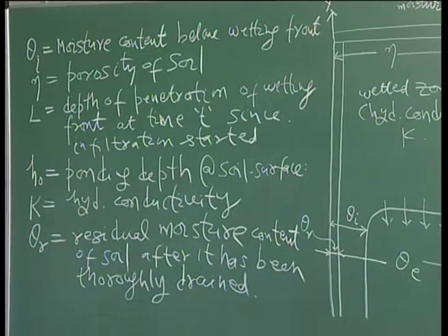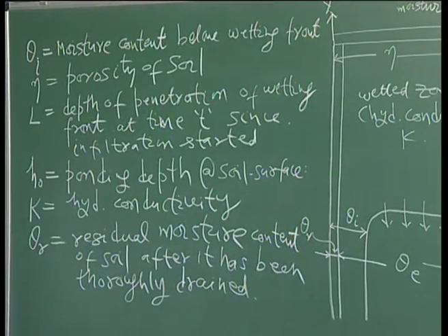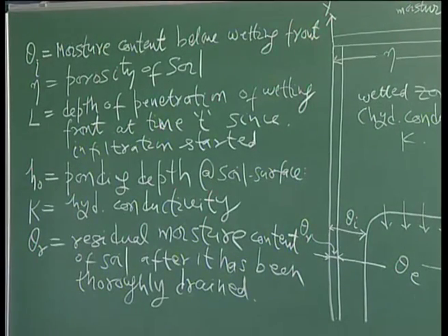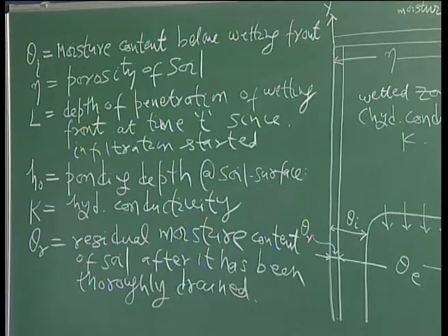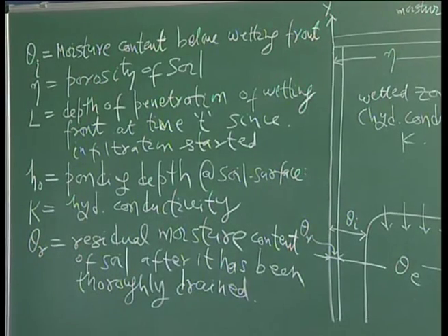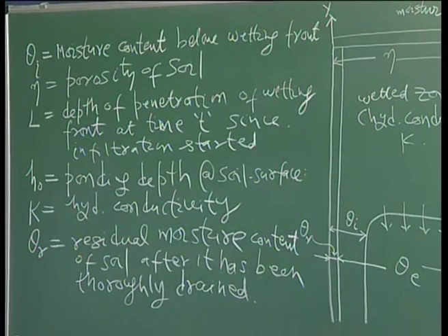I am sure you understand what we mean by this concept of residual content: if we take a sample which is moist and we start draining it, we just leave it, most of the water will run out, but some water will be held back, which is called the residual moisture content. Different soils will have different residual moisture content, so it is a property of the soil.